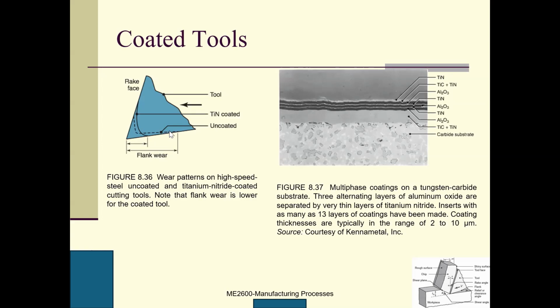Why? Because the configuration of your flank surface changes, and if the flank surface is changed, your tool will rub the machined surface. So know that the flank wear is lower for the coated tool.